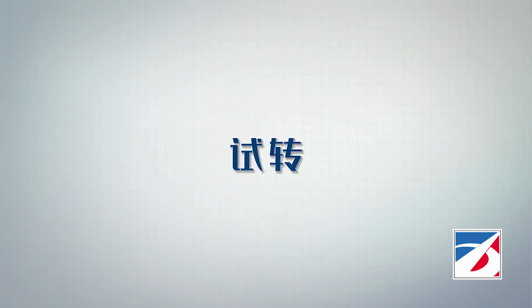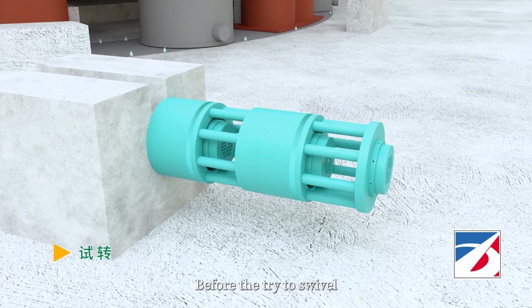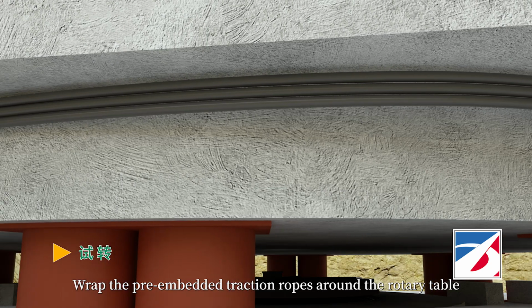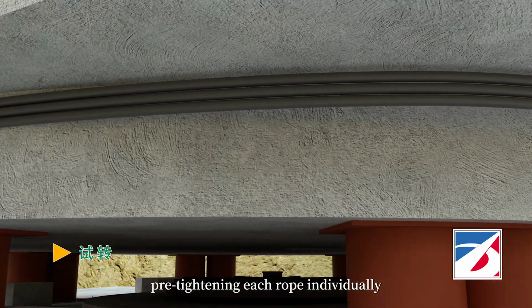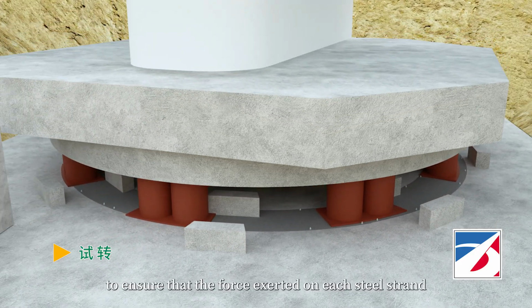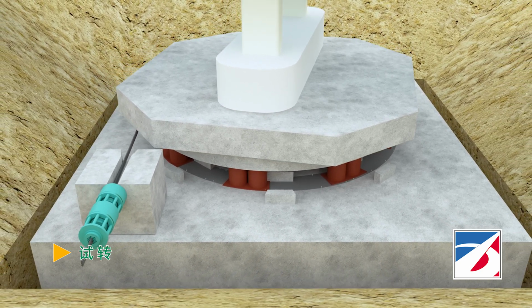2. Trial swivel. 1. Before the trial swivel, conduct a no-load test of the equipment. Wrap the pre-embedded traction ropes around the rotary table and pass them through the jack, pre-tightening each rope individually to ensure that the force exerted on each steel strand of the 2 traction ropes is basically consistent.